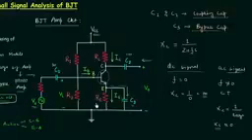Now why are we so desperate to short circuit the resistance Re? The gain reduces because of resistance Re, and if we short circuit the resistance Re, the gain will increase. I will explain why gain reduces because of Re in the coming presentations, and this is all you need to know about the BJT amplifier circuit. C1, C2 and C3 are very important: why they are used, how they act as open circuit for DC signal and how they act as short circuit for the AC signal.